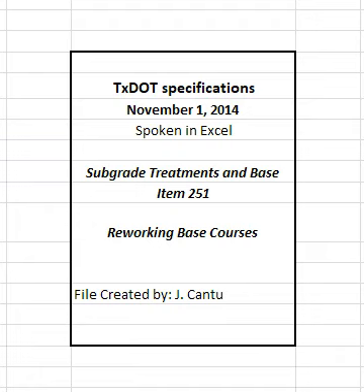6. Payment. The work performed and materials furnished in accordance with this item and measured as provided under Measurement will be paid for at the unit price bid for Reworking Base Material for the type, scarified depth, and compaction method shown on the plans. For cubic yard measurements, the measurement location, vehicle, stockpile, or original position, will be specified. No additional payment will be made for thickness or width exceeding that shown on the typical sections or provided on the plans for station, square yard, and cubic yard in the original position measurement.